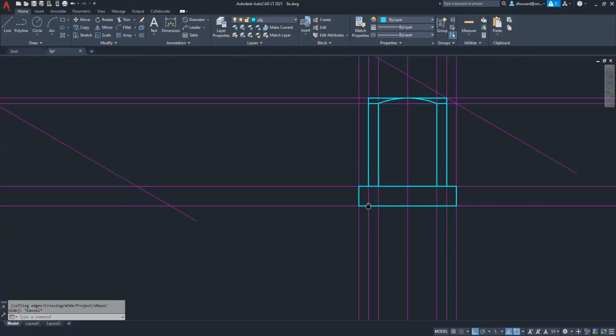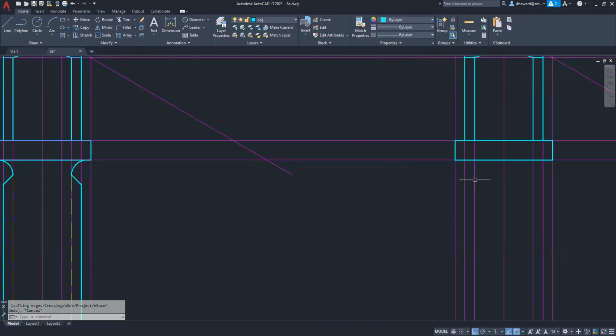Let's keep working down. Where the threads of the bolt intersect the head, we are told that there is a 3/32 radius in addition to the standard chamfer that would be there. So I included that, and it wasn't spec'd out, but when threads are created, that is something that is done. But in addition to the threads, we have this rounded chamfer. I'm sorry, fillet. Sorry.